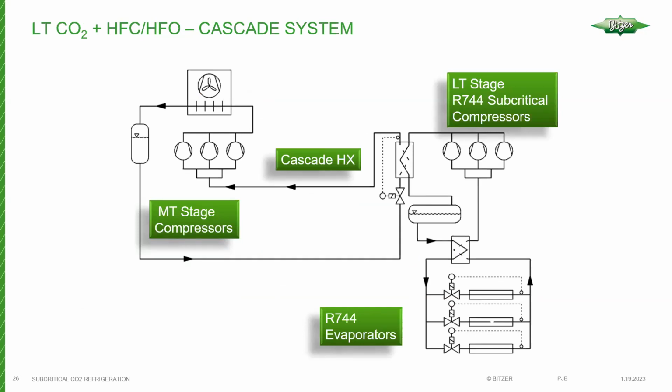Another approach is typical of a cascade system. This will be similar to, if you're familiar with them, ultra low type systems that operate in cascade. You have two compressor circuits, and you'll generally have two refrigerants, and one refrigerant will be more volatile than the other. As it turns out, it also happens to be a higher pressure. So, for example, on the low side, it would be something like R23 or 508B or something like that, and then you would have, it could have been 404 or 507, nowadays perhaps 448, 449, something like that.